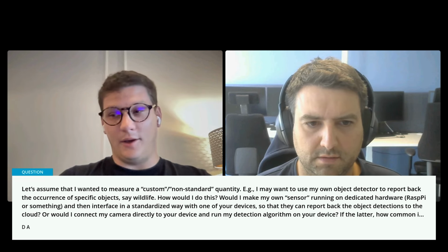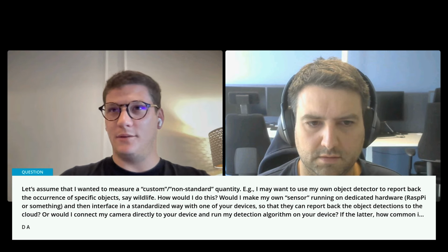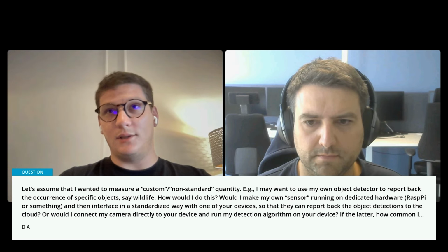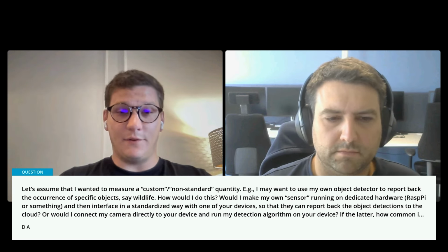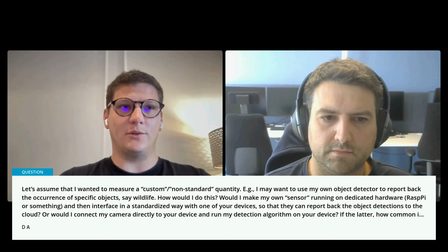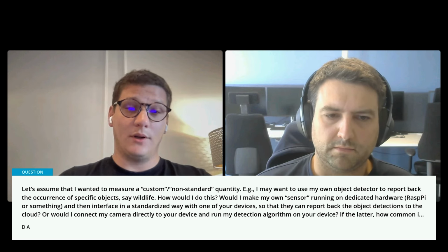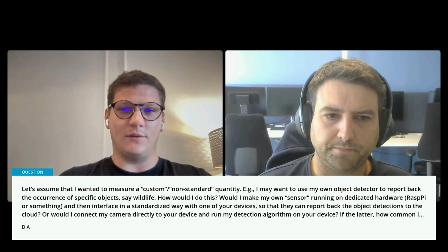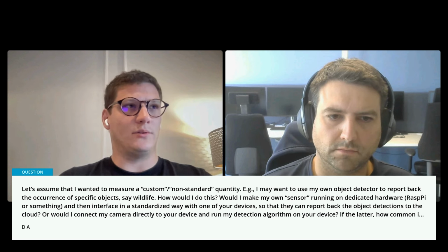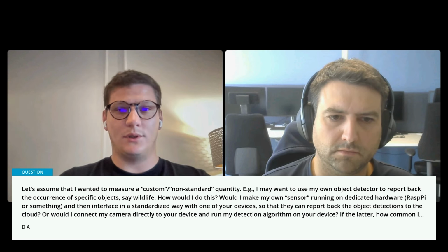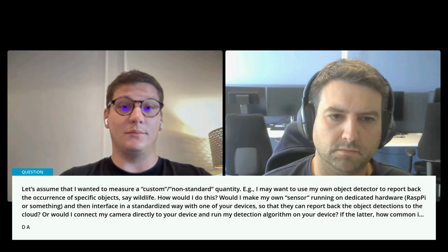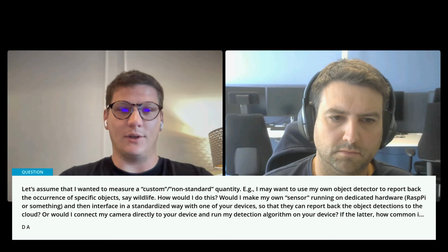Yeah, I totally agree with everything you've said, especially with the sensor subsystem in Zephyr. The abstraction layer is quite high, so the learning curve is quite steep, but because of that, you are able to quickly transition between development boards, architectures, and sensor systems you are using on your product.